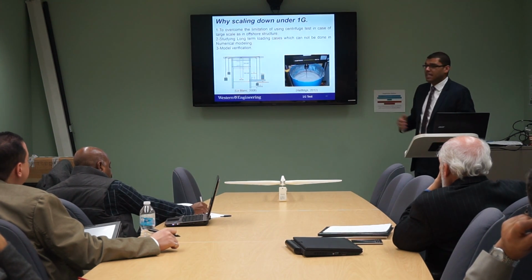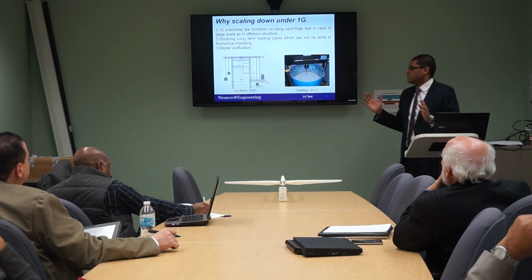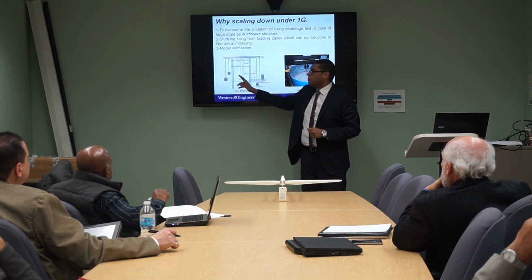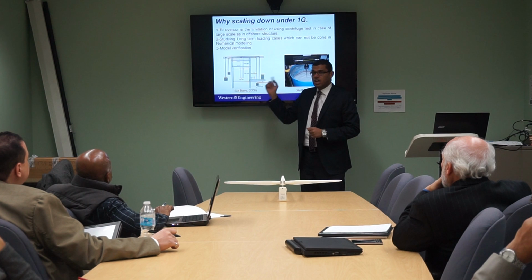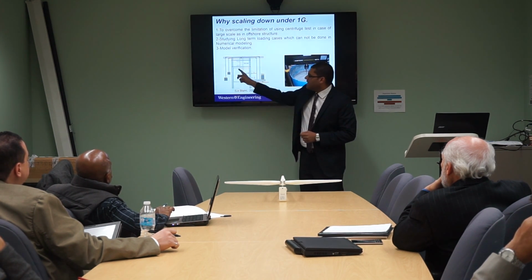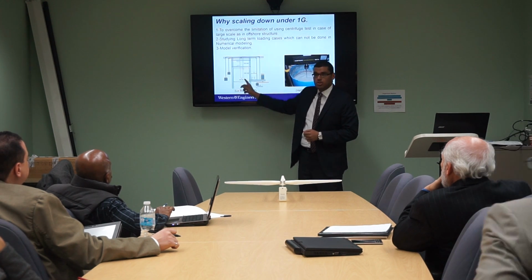So what's the 1G scale down test? The 1G scale down test is geometrical scaling of the model itself, but not the soil, under gravity. So it will be studied under just 1G. We'll see how we are modeling or scaling down the soil here.